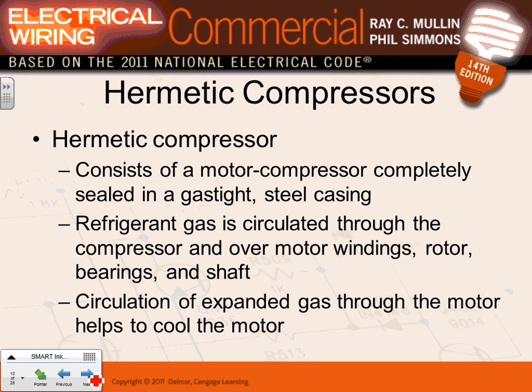Hermetic compressors. The term hermetic compressors, guys, is really interesting. This is how they define it. It consists of a compressor and motor combo completely sealed in a gas-tight steel casing, all in one gas-tight steel casing. Who cares? If it's a hermetic compressor, Jeff, we can allow this pump to work much harder than if it wasn't, and you're going to know why. The compressor is completely separated from other pumps. The reason is the refrigerant gas, look what they do.